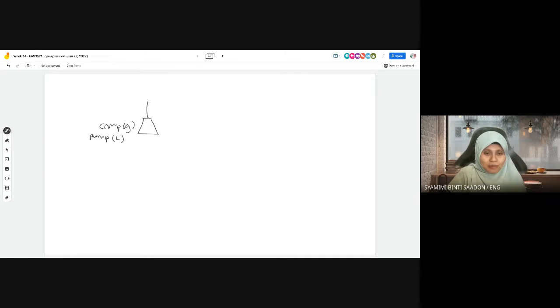So you have the compressor first, and then you have something to increase the temperature, to evaporate, to boil. So you use a boiler, to boil and to exchange heat with the heat source. We use the boiler for liquid. For air, gas, vapor, we use an evaporator. And for a jet engine, this is replaced with a combustion chamber.